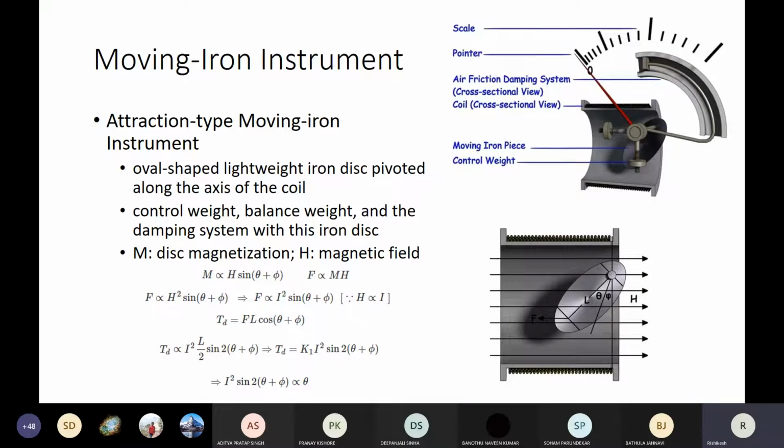So, in fact, you must have seen already that PMMC and electrodynamic instruments are deflection type instruments, wherein the quantity of interest develops a particular type of movement in the pointer, and that pointer movement is calibrated in terms of the quantity under measurement, whether it is voltage, current, or something like that, right? So both PMMC and electrodynamic instruments can be used as ammeter or voltmeter. However, the electrodynamic instrument is mainly suited for power measurement, that we'll see later when we discuss power measurement techniques.